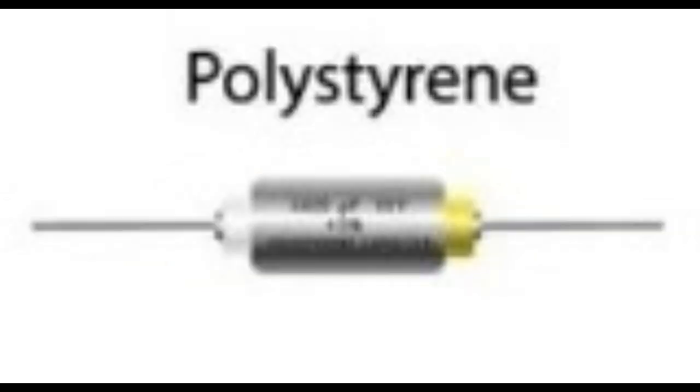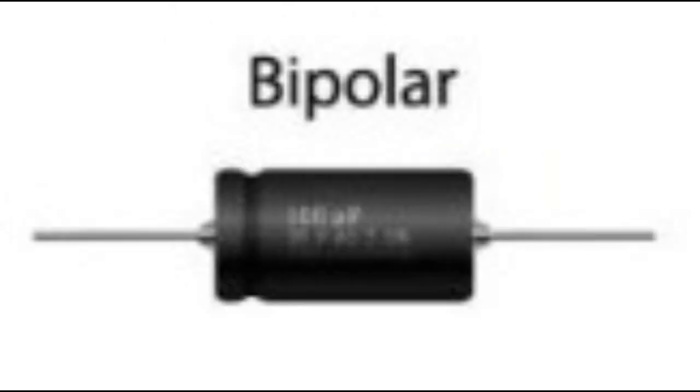Polystyrene capacitor properties. These capacitors provide high insulation, low leakage, low dielectric absorption, low distortion, and excellent temperature stability. In view of their properties, polystyrene capacitors can often be used in place of silver mica or ceramic disc capacitors. Polystyrene film capacitor.